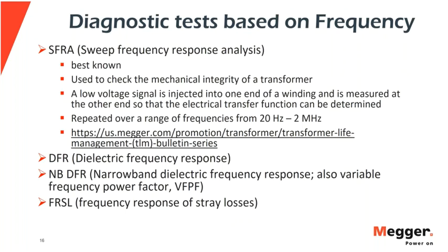Before I do that, though, I want to mention that several diagnostic techniques are based on frequency, and those include SFRA, which is sweep frequency response analysis, dielectric frequency response DFR, and narrowband DFR, which we are talking about here today, and FRSL, or frequency response of stray losses. Each of these tests is unique, so it's important that you understand the differences between them.